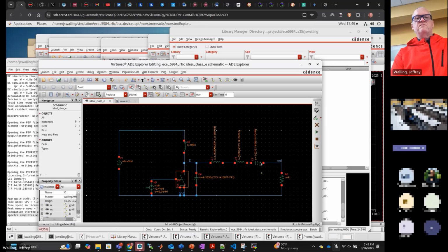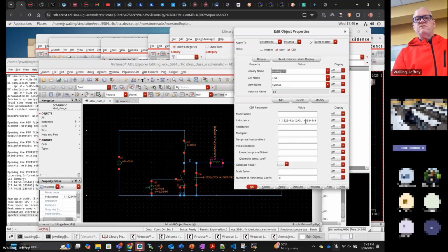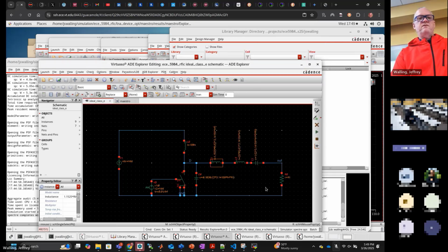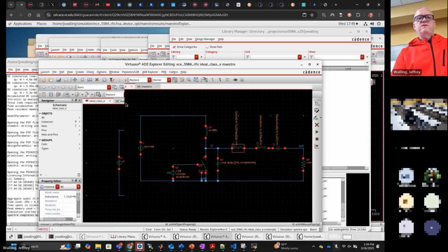And then I calculate whatever these components need to be in order to achieve resonance. These are all entered as variables. I wanted basically everything in terms of FRF, RL, and the supply voltage, if possible, and Q, the network quality factor.